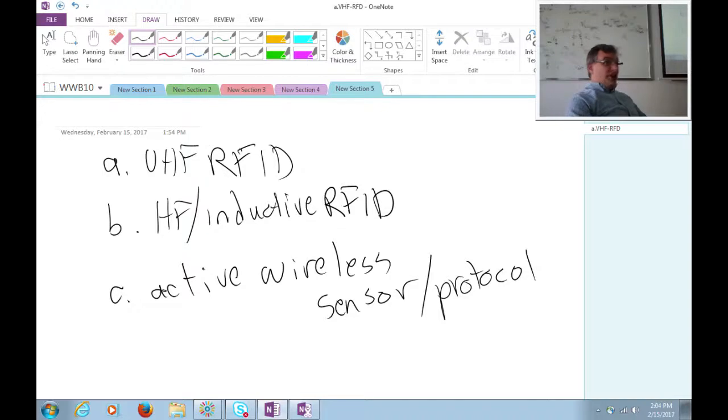You do have to worry about changing batteries, right? But for this type of system, something low energy that basically turned on in the presence of a beacon and otherwise slept, you can get those things to last for a couple of years now, at least 3-4 years, on a single coin cell type battery. And obviously, the HF inductive RFID, that's always nice for passive systems. You don't have to worry about it on the human body, but you won't get a range of 3 meters, unless you've got a red hot inductive coil around your door or something like that.